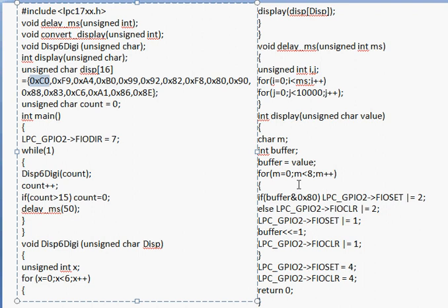So what basically it does, let's talk. What is the value of buffer? Buffer value is C0. C0 you AND with 80, bitwise ANDing you do. So if that is the case, you get the result as 80 itself. Think of it as true, which means you have some information. It is not 0, which means this condition will be executed, which means 1 is sent.